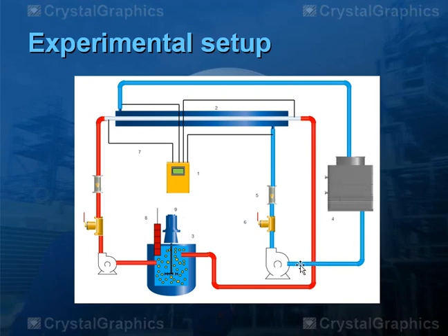The cold water is pumped into the shell, and the hot water is mixed by an agitator with the nanoparticles additives and heated, then pumped into the tube in countercurrent configuration pattern.